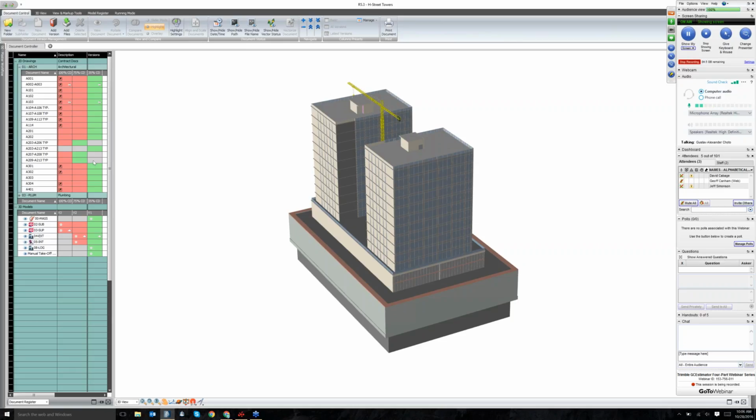So as is the case in construction, whether you're building or you're bidding work, we're constantly getting addendums and changes or bulletins to the drawings. What we can do inside of Vico Office is publish as we go along. So as you can see, I have 35% drawings that have come in. Now I have 75% and 100%. So during the process of iterating on a project, we would bring those drawings in, and the moment that we publish those drawings, one, we vectorize them. So whether it's a rastered PDF with no intelligence, we can read the line work, so you can snap to lines, and also analyze the line work.